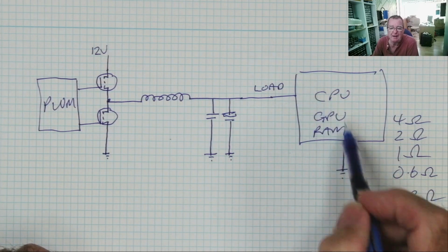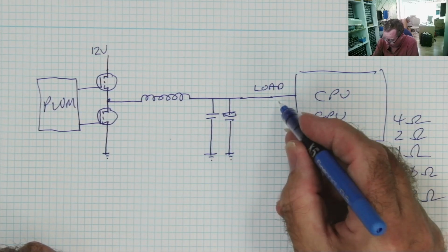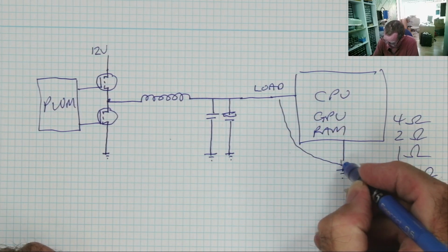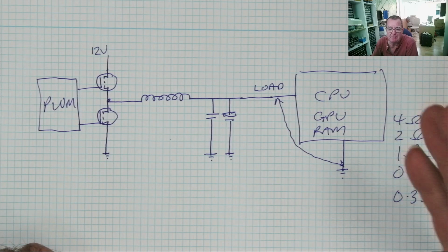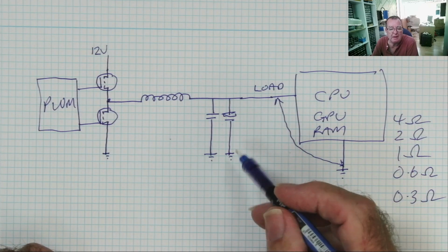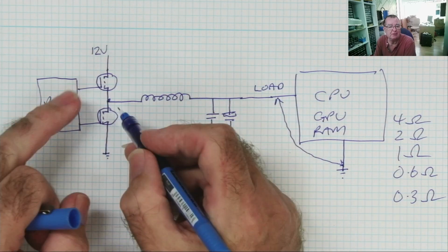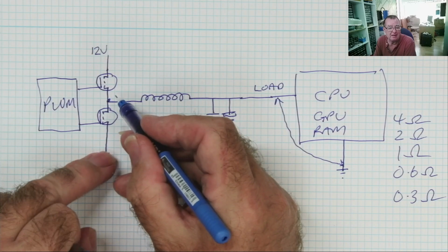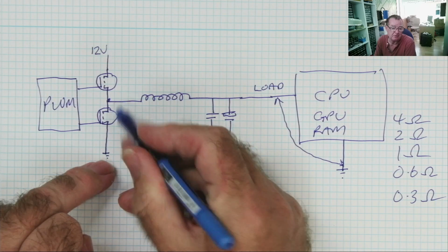So you effectively have, as far as your meter is concerned, what looks like a short here. It's not a short, it's just a load that has a very, very low resistance naturally. Now, if you use diode mode and you want to check these MOSFETs, this one, or if you like from here to ground, it's the same thing. Look, ground is there.